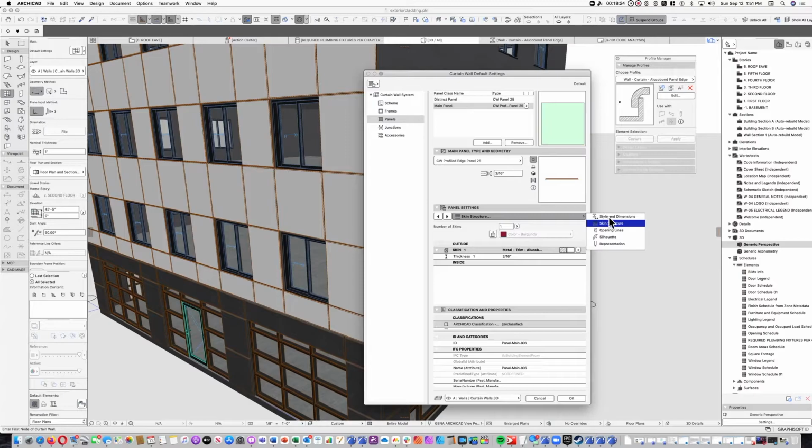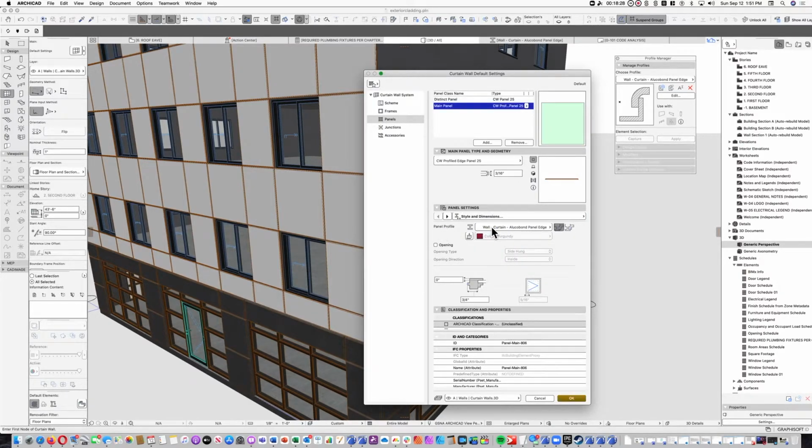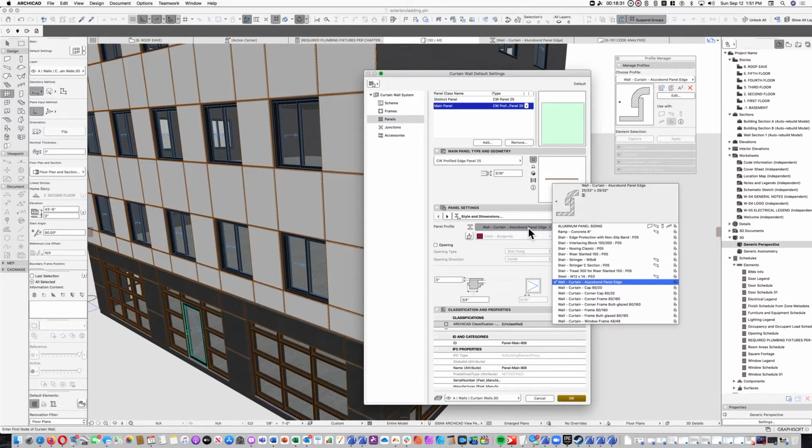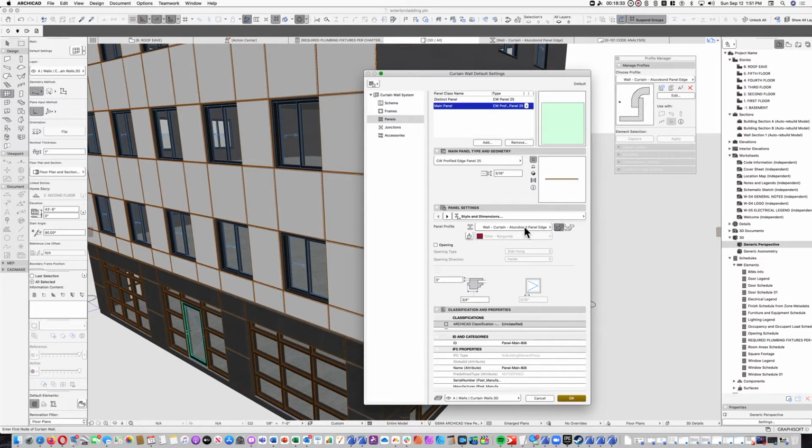So then we're going to go down here to the settings and we're going to choose the profile, in this case the one that I created before, and I opted for the profile origins position aligned to inset, but you can play around with these and see what the effects are. I turned off the opening, set this to 0, and made the width 3/4 of an inch, and so now we move on to the next.